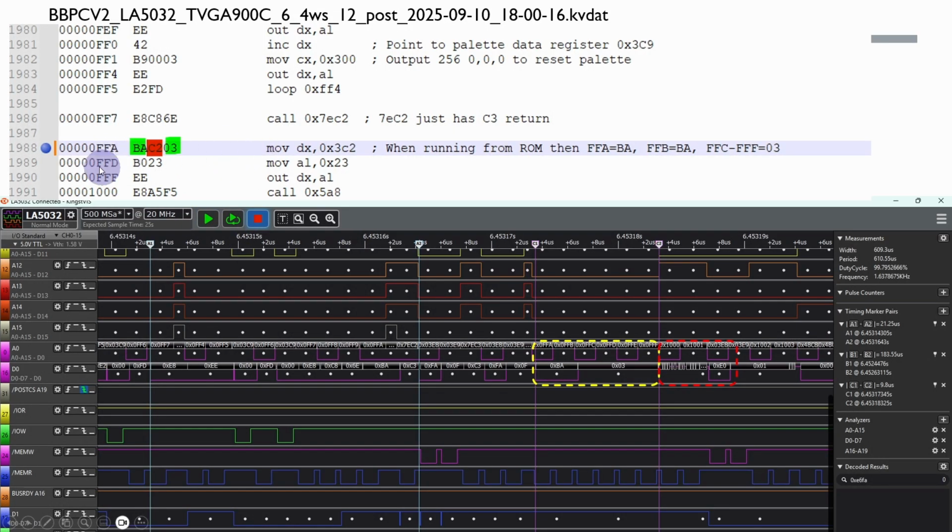So again, that would indicate that despite it actually reading through quite a bit of the ROM, from time to time we're getting these sorts of corruptions from reading the ROM. It could very well have been caused by these bus timings that I've been talking about.